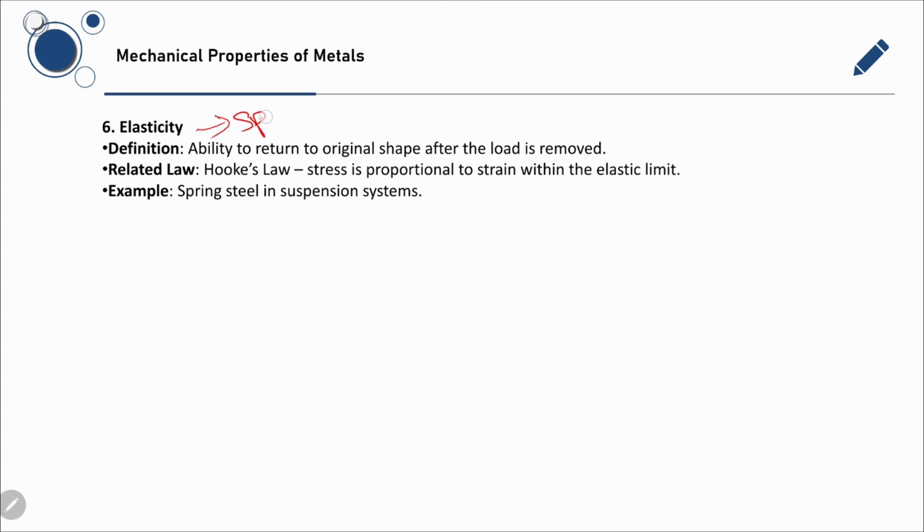Elasticity means springs back, in simple words. It's a material's ability to return to its original shape once the load is removed. Within the elastic range, stress is proportional to strain. This is Hooke's law. If we put a little load, it stretches a little and springs back. If we go past the elastic limit, it won't fully return. That becomes plastic deformation.